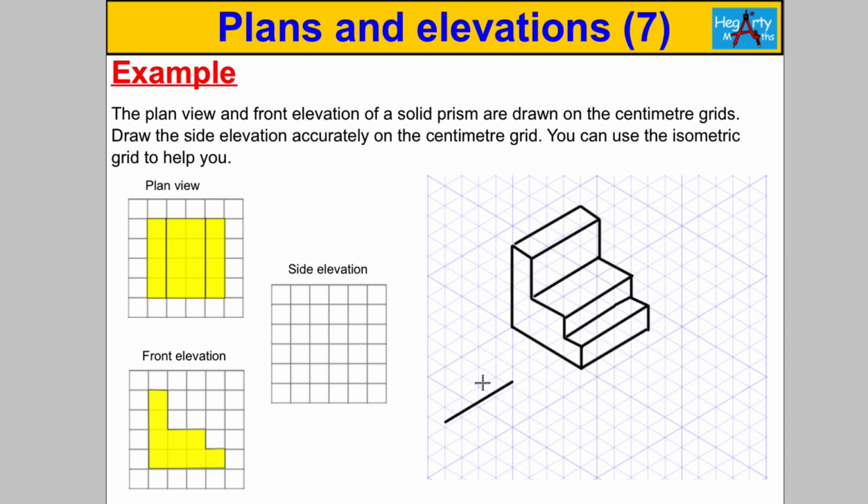Now that's the front, which we knew about. Does the plan match this? Yes, it does, because you see a bar of 1 by 4, which would be this. Then you see a bar of 2 by 4, which is this, and then you see a 1 by 4, which is that. Now, what does this thing look like from the side?